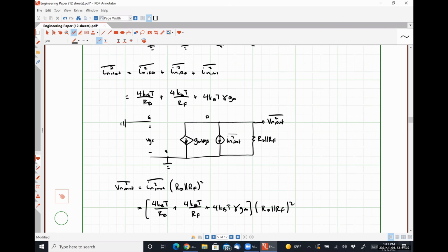All right, so we'll wrap this up on Wednesday, talk about differential pairs very briefly to move into that single stage op amp, which is just a differential pair loaded with a PMOS current mirror, so that we go from double ended output to single ended output, which is what we expect.